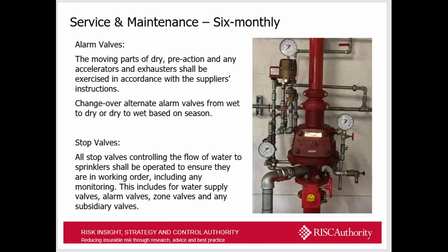Stop valves. All stop valves controlling the flow of water to sprinklers shall be operated to ensure that they're in working order, and this includes all water supply valves, alarm valves and zone valves and any other subsidiary valves on the system. The picture on the right hand side there shows a standard dry alarm control valve set. This is just permanently charged with air, water up to the valve and air on the other side, on the pipework side.